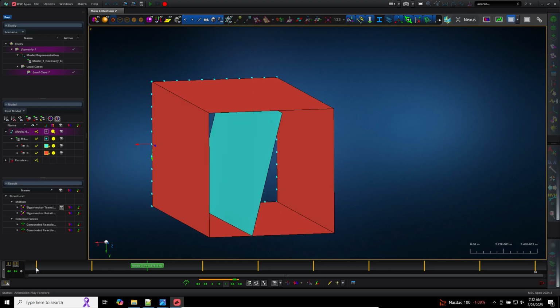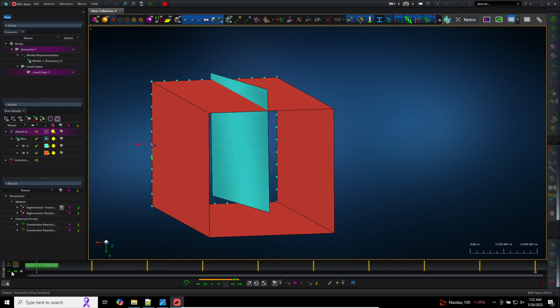You know something is not attached when the natural frequency is very small and close to 0. Here at the bottom left, if you look at the natural frequencies, you have 3 times 10 to the negative 4 Hertz. To the negative 4, it's very small. It's effectively 0. If you go to the next mode, same thing. It's 2 times 10 to the negative 4.